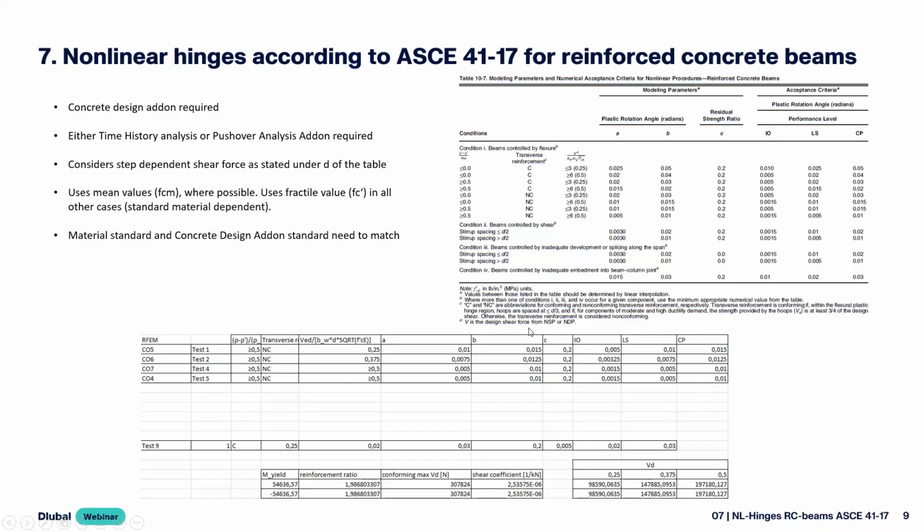V is the design shear force from NSP, so for pushover or time history. It uses the actual shear force for its behavior. That means the hinge behavior also is iterative, which is one more non-linearity and makes it quite complex. But it's working. That's quite cool.